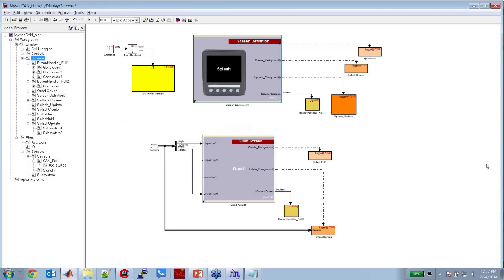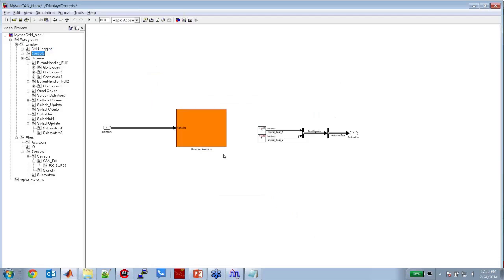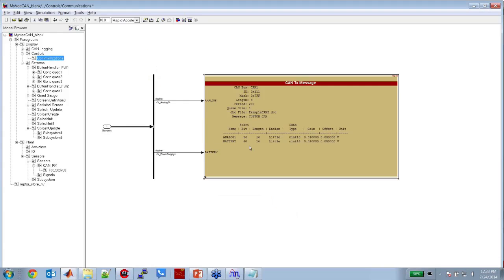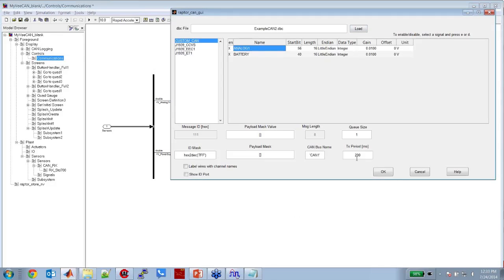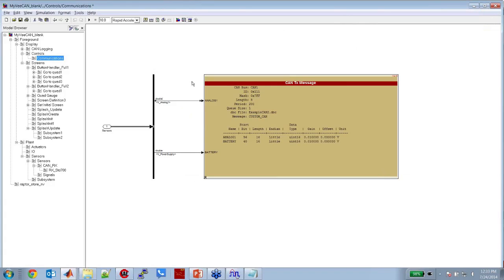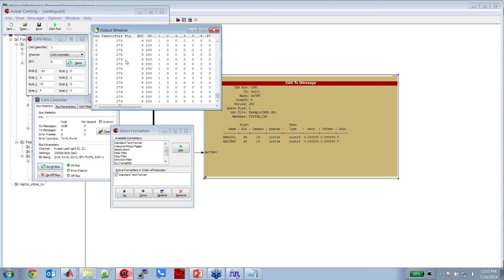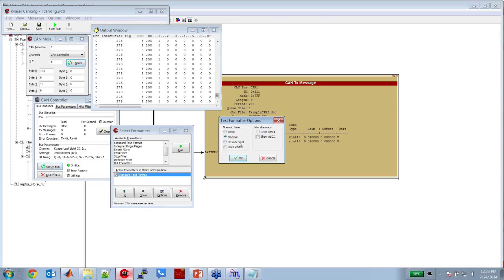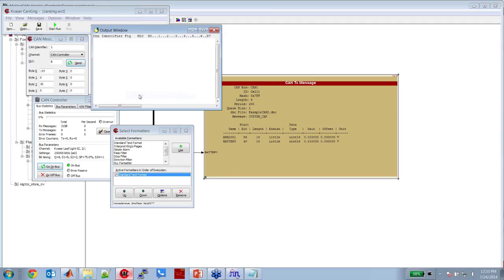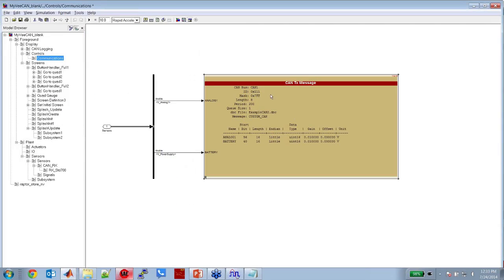Okay. Can the display be used to send values to the ECU? For example, calibration of some values inside the ECU. Yep, that is just a simple CAN transmit message here. In this CAN message, we are sending out the analog 1 value we read from our analog input as well as the power supply, and that gets transmitted onto the bus in this CAN message. So ID 111, that's in the example template project.